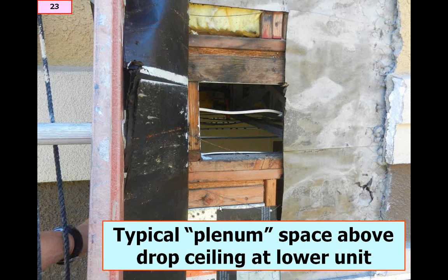For this building, what we found for this project is that there was not complete sheathing or closure behind the belly band. It simply looked exactly as we see here. There was the polystyrene foam belly band positioned over building paper, positioned over the ceiling cavity that separates the two units, and you can see inside actually the metal work that forms the drop ceiling of the lower unit. The second floor unit then starts in essence at the sill plate that we see higher up the wall.